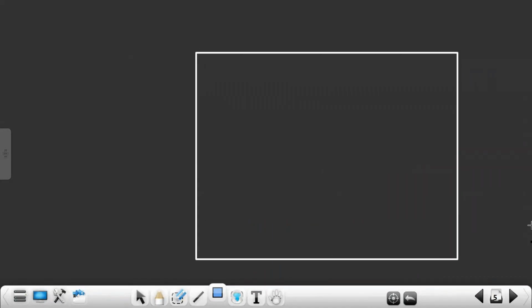See, doing the physical design for the full chip is very difficult. The runtime will be very huge. Runtime means if I type only one command like place opt or clock opt, that one command will take 18 or 20 hours to complete. Full chips have millions of gates, meaning 10 lakh or 15 lakh cells, so the runtime is very huge.